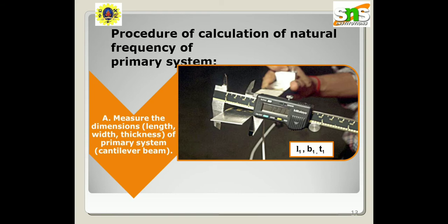The natural frequency of primary systems: tuned mass dampers stabilize against violent motion caused by harmonic motion. A tuned damper reduces the vibration of a system with a comparatively lightweight component so that the worst case vibrations are less intense. Roughly speaking, practical systems are tuned to move the main mode away from a troubling excitation frequency.